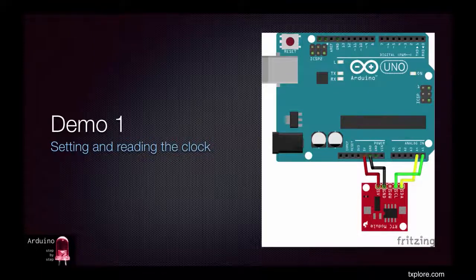I will be using the DFRobot DS1307 RTC breakout, which I purchased on eBay for around $4. This device, like many others, is based on the popular DS1307 clock IC, and it can do anything you would expect a good clock can do. It counts seconds, minutes, hours, days, years, goes up to 2100 and compensates for leap years. It also consumes very little power, 500 nanoamps, which when using the onboard battery gives the device a life of around 5 years.